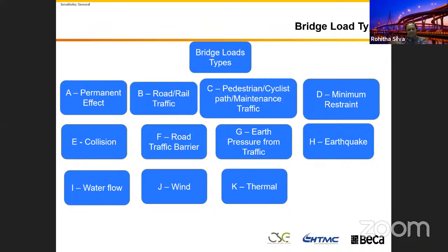What some people do, they get a few hundred load cases, run this one, get a maximum bending moment diagram here, minimum bending moment diagram, design the reinforcement, put it in there. Then someone asks you to present to, for example, your client, this is my bridge design. The client asks, I don't know anything about bridge design because I'm a project manager, but just for my understanding, I want you to explain which load case governs this design.